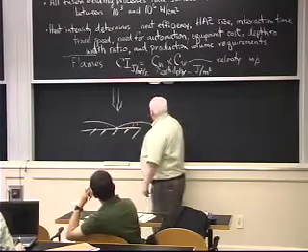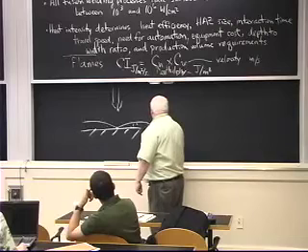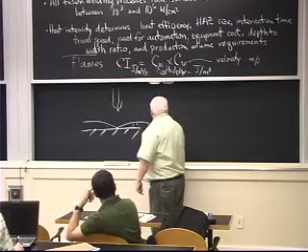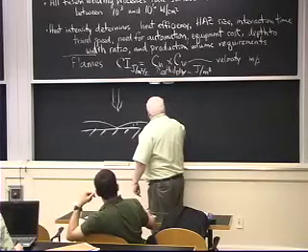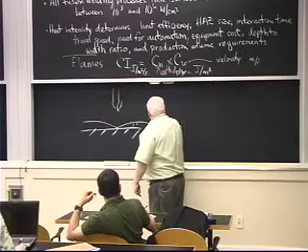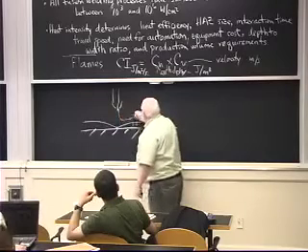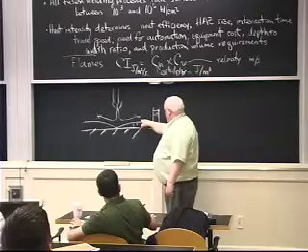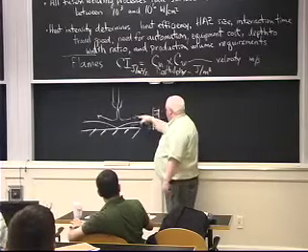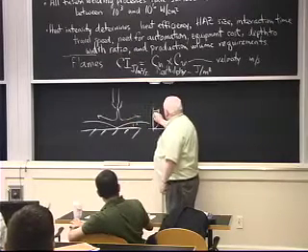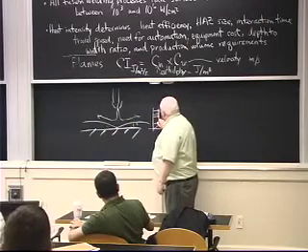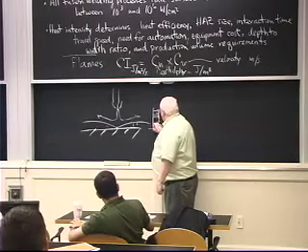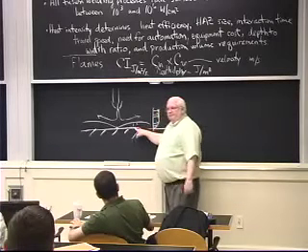But you have a boundary layer, and this is relatively stagnant air. If you remember from having studied boundary layers, you draw the velocity profile, it's zero velocity up to a free stream velocity. So the hot gas is coming in, hitting the surface and turning the corners, you have a free stream velocity, but down in the boundary layer, the velocity drops to 0.